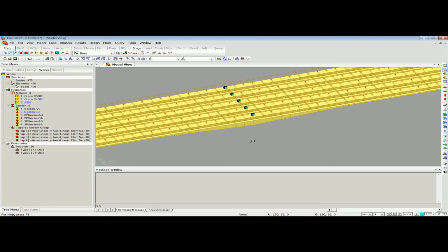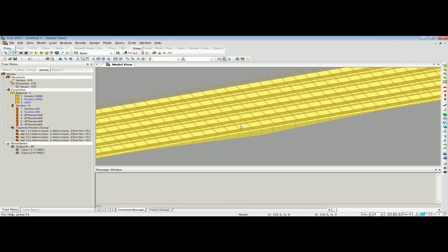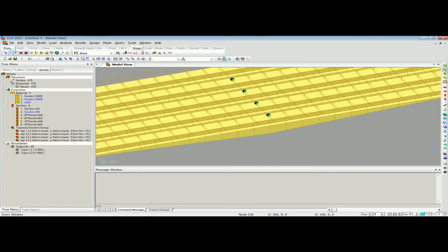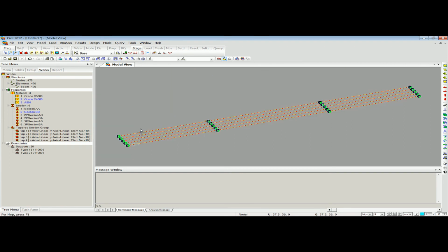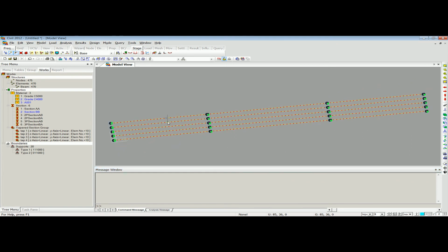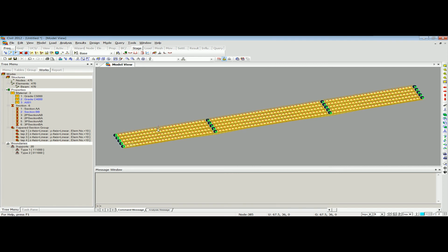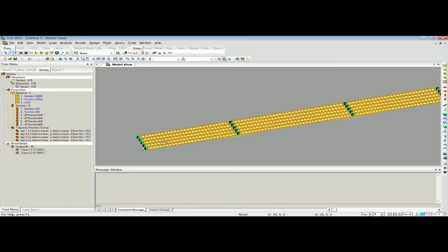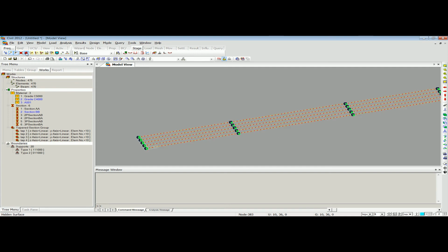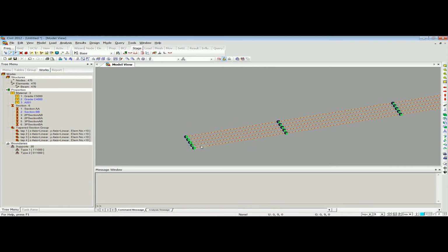and you will see that on the top of the girders we have the slab too. But if you see the line beam model, you will see that there is no connection whatsoever between the girders in the transverse direction, because the composite section will model the slab for you in the longitudinal direction of the bridge, but for the transverse direction you have to consider the slab stiffness by using the beam elements, because it's a grillage model. So now we'll create the beams in the transverse direction.